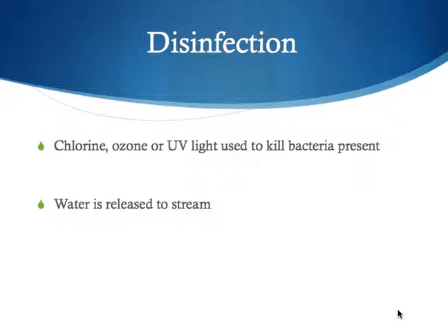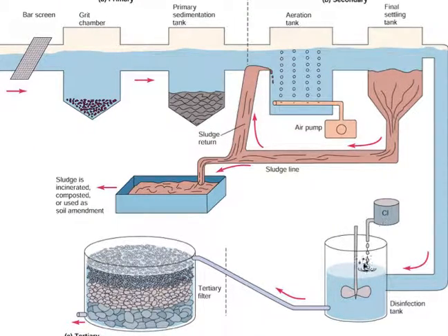It's possible that if we're using chlorine, we're going to need a long contact time, and we're going to have to remove excess chlorine with sulfur dioxide before it goes out into a waterway. Okay, so that's our wastewater treatment plant.